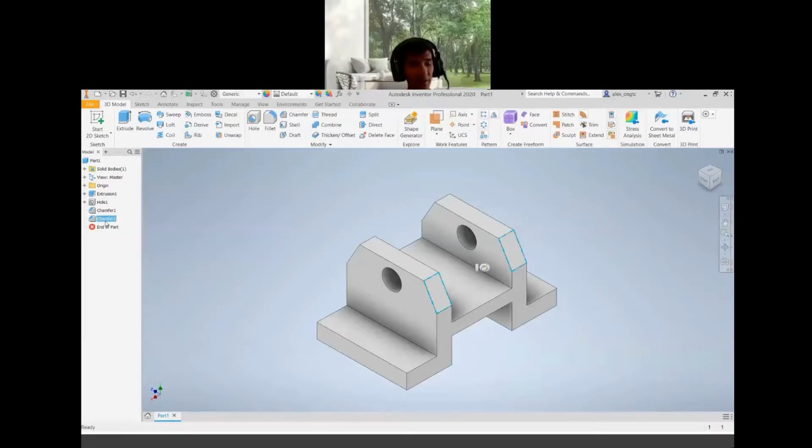Okay. Of course, you can see from the browser, as I say in Inventor, it's very important for you to take notes whatever happened in the browser. So if you make a mistake itself, you can always delete it from your browser. Don't go undo. Okay, so I delete my second chamfer here. You will return back. You only have chamfer on the other side. Okay, so chamfer. So please go to chamfer.